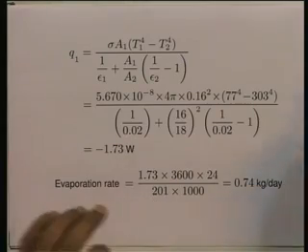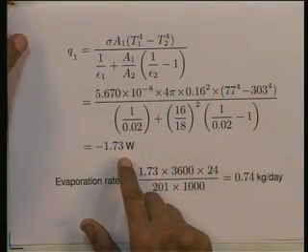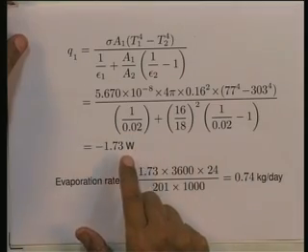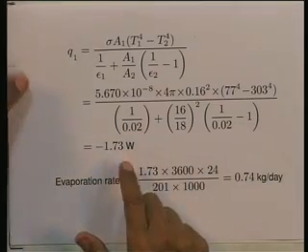All right. Now, I want you on your own to show that the resistances which we ignored, that is the two convective resistances and the two conductive resistances, are in fact insignificant. We have studied conduction, you know the values of h that you would get in convection, you should be able to show that they are insignificant and that the temperature drops across those would be insignificant compared to the temperature drop that we encounter in the annular space.